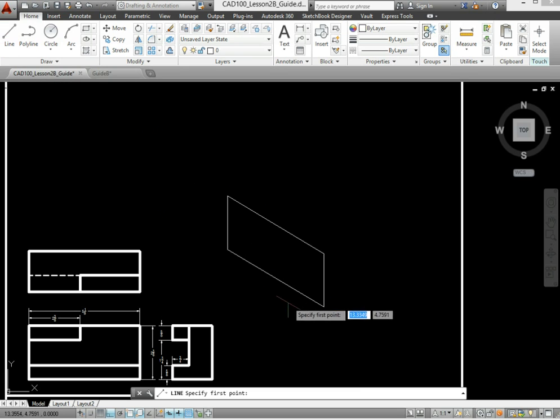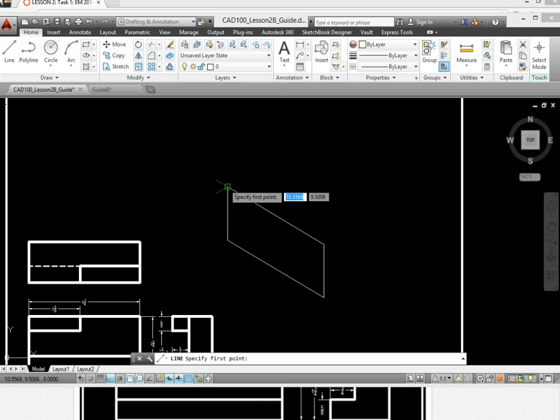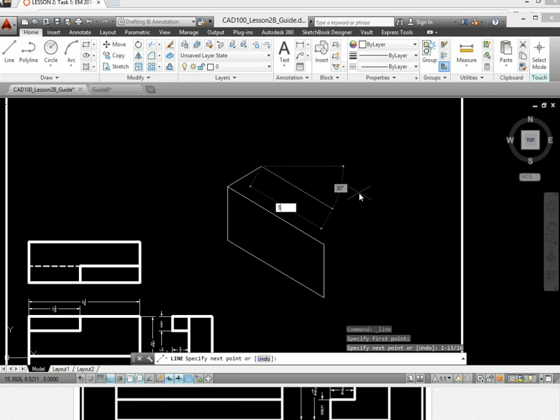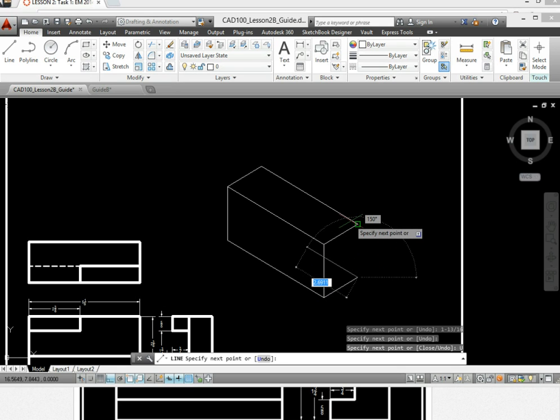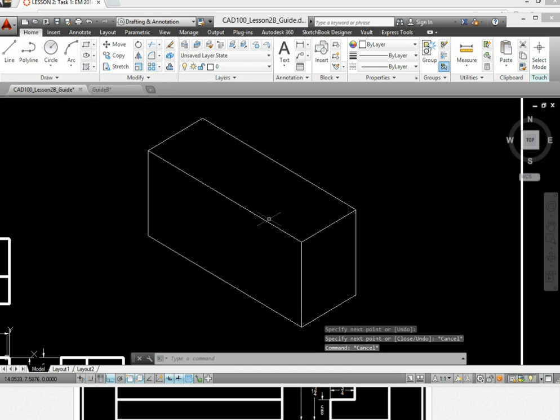Pick the line command. Hit F5 with the top now, which means depth and width, which is the depth. This is 1 13/16. Same width. Click here. If you make a mistake like I just did, you can use U to undo. I'm grabbing that endpoint even though my F5 key is in the wrong direction because I know that's going to snap to it. So we start here.